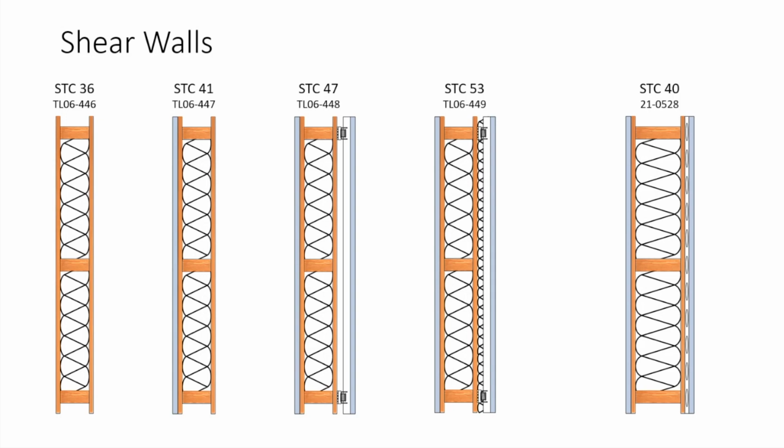So again, this is one structural path and cavity path. So we use the isolators to isolate that structural transmission path, but here we need the insulation to reduce the transmission through that cavity path. And we need a big enough gap, a big enough airspace between that shear layer and our drywall, so we can, one, put insulation in the cavity, we just have room for it, and it lowers the mass air mass resonance. It just makes the acoustic isolation more effective, we'll say.